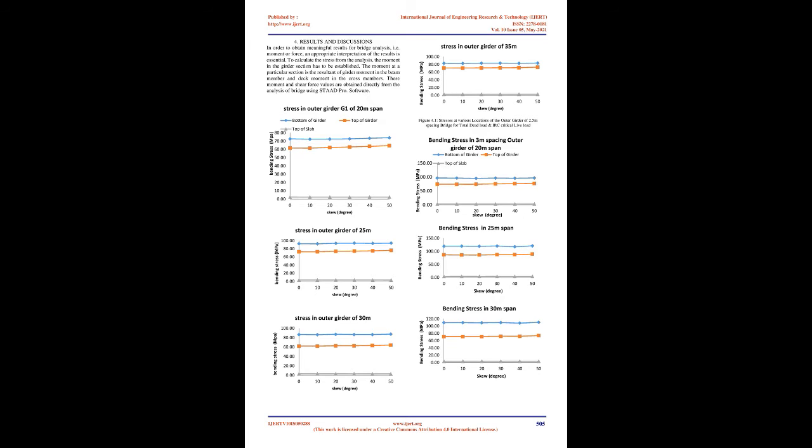The mesh of the space frame in plan is identical to the grillage, but various transverse and longitudinal members are placed coincident with the line of the centroids of the downstand or upstand members they represent. For this reason, the space frame is sometimes referred to as downstand grillage. The longitudinal and transverse members are joined by vertical members, which, being short, are very stiff in bending.